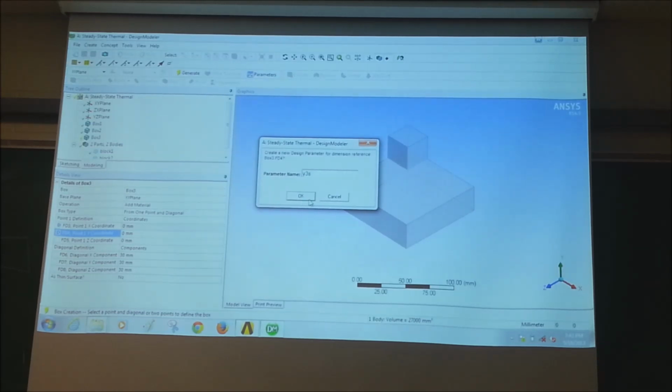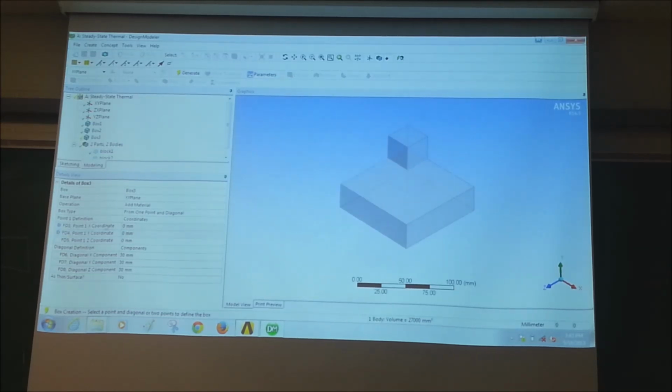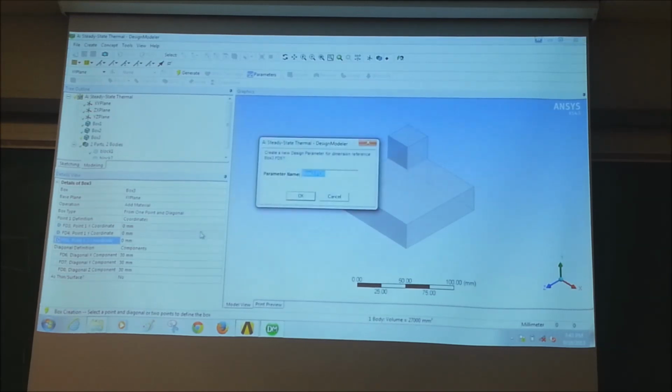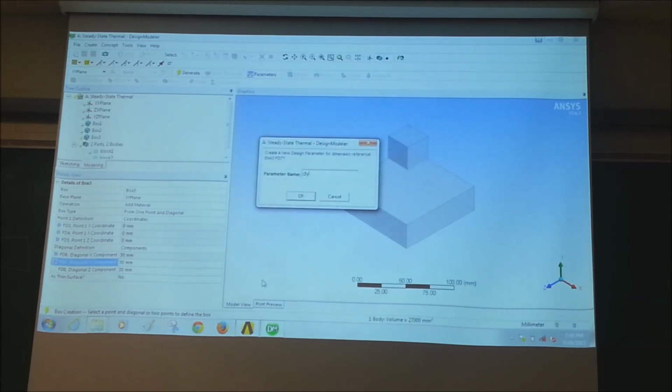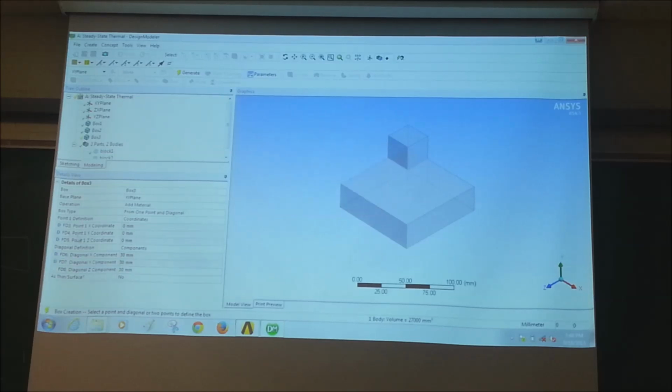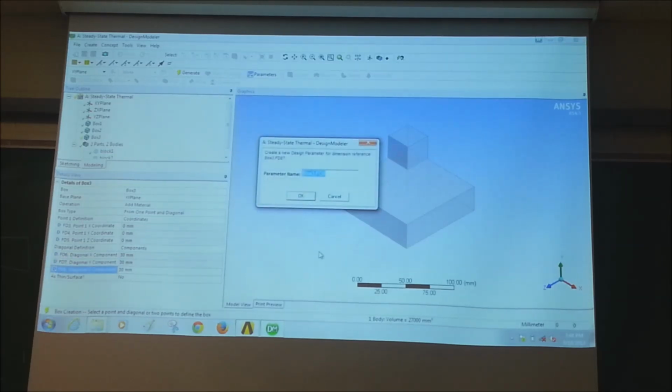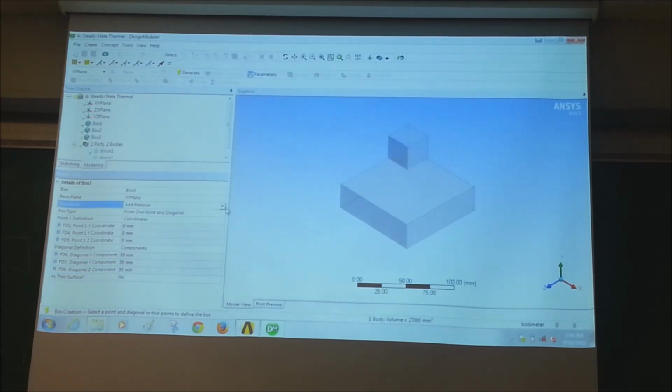So supposing you forgot it, you just put a variable there. So Y3S. And this is going to be Z3S. All right? And this is going to be DX3, right? DY3 and DZ3, and we're going to say add material, add frozen, so generate. So I don't know where it's going to be, someplace, right?